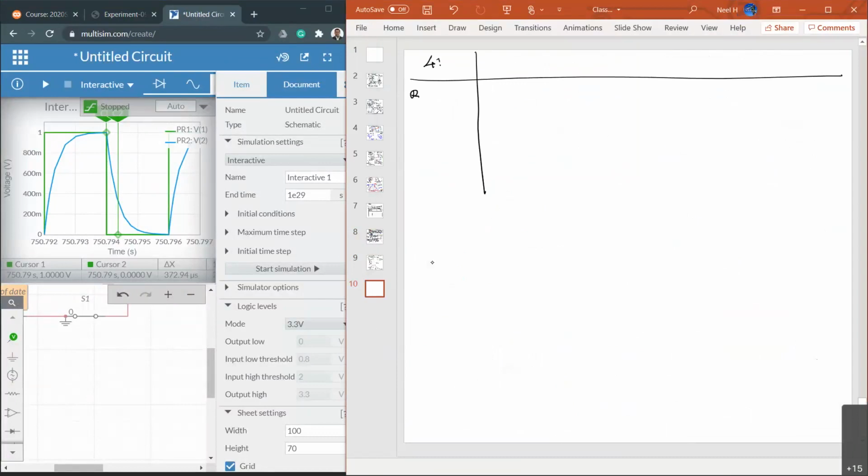In circuit number 4, the resistor is going back to 100 kilo, only one resistor. Now I have two capacitors. C1 is 10 nano and C2 is 15 nano. Now tau calculated, unit second. You know tau is R times C. To get that, I need the effective capacitance between these two. The resistor value we know is 100 kilo, 100 times 10 to the positive 3, but the capacitors are serially connected.